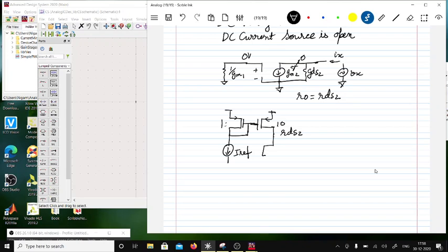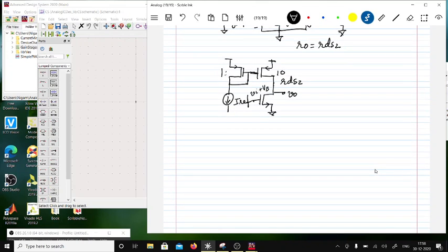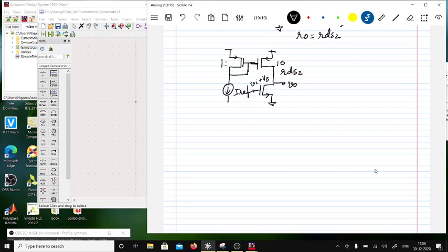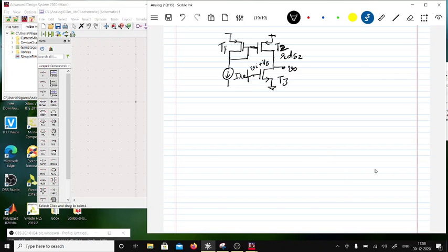And then there is going to be a gain stage here, okay, where I will put Vi on top of a certain bias, so this will be VB. So I'll put a Vi on top of a certain bias, and then I'm going to tap the output voltage over here, right? So now in this case, this is T1, this is T2, and this is T3. So for T3, let's say the output resistance is RDS3. So now let me draw a small signal model for this.